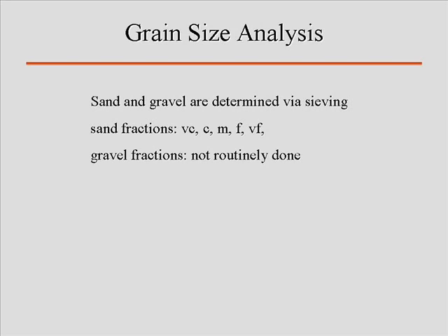And you're going to have to heat up those filter papers at lowest temperature. I don't care if you bake the clays now, but you need to dry off all the water that was contained within that aliquot. And because you're going to be heating the filter papers up to weigh them, you have to follow the same methodology to start. So you weigh the filter papers blank after you've heated them.